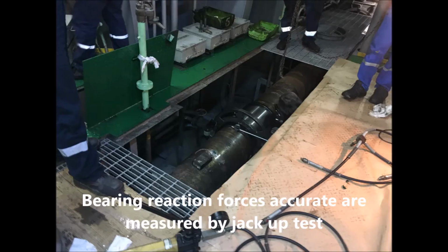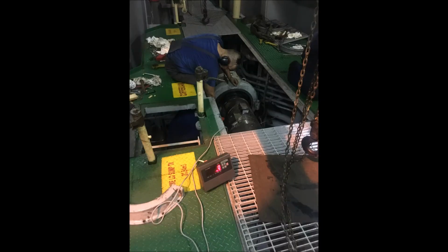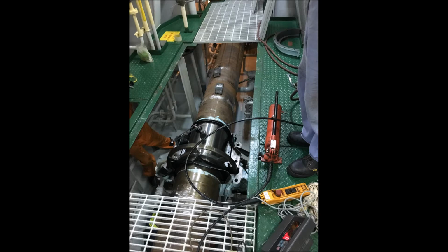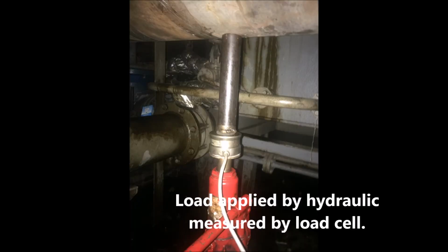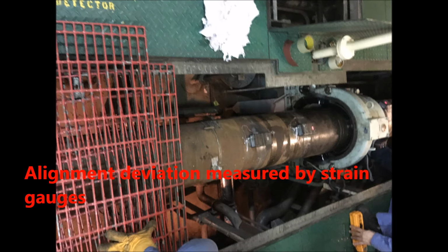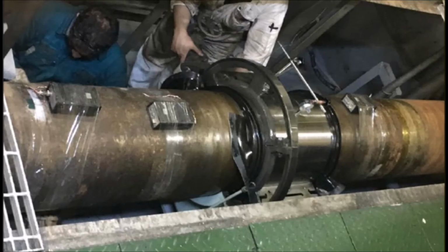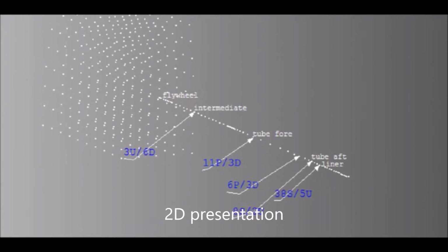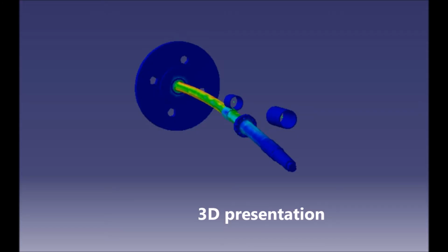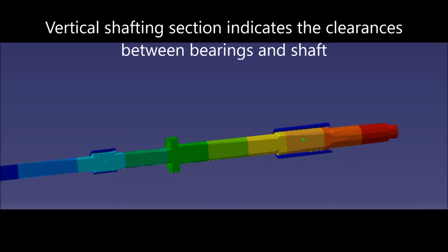Bearing reaction forces are accurately calculated by finite element software and are measured by jack-up test and strain gauges. Alignment deviation is measured by strain gauges without any shafting dismantling. The presentation will be in 2D or 3D. A direct comparison of alignment deviations with the ideal condition, brown, is presented.